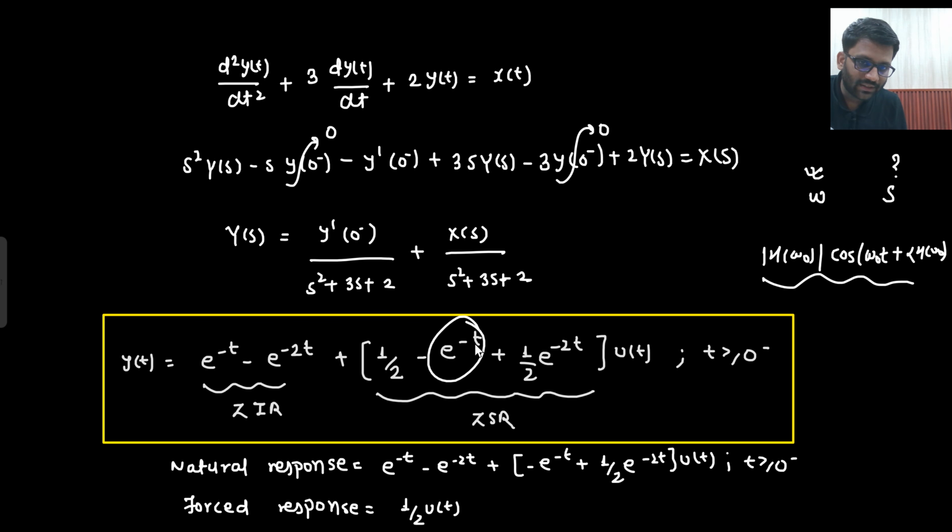Look, here you can see the transient part. These are the transient parts. They will die down at t equals to infinity. At t equals to infinity, everything will die down. Only this forced response will be there. So if you solve any circuitry in omega domain, you will only get the forced response. If you want the natural response, you have to use Laplace transform. So the first advantage is this one.